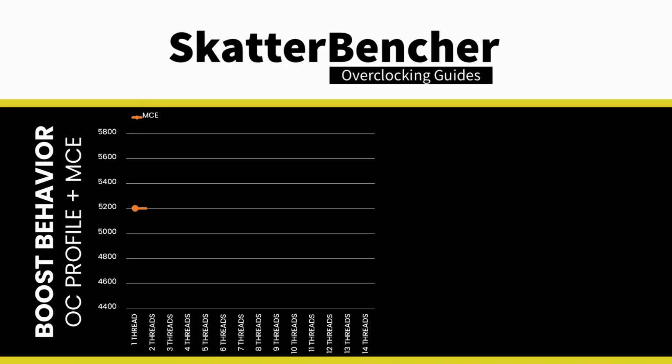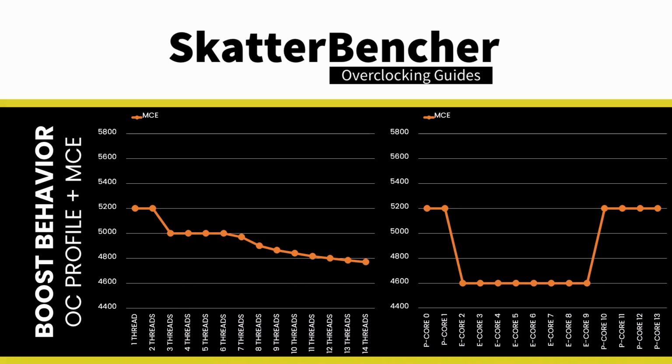the CPU boost frequency with one active P-core is 5200 MHz. The average boost frequency gradually trails off to 5000 MHz when all P-cores are active, and to 4771 MHz when all P and E cores are active. Every P-core can boost to 5.2 GHz, and every E-core can boost to 4.6 GHz in single-threaded workloads.